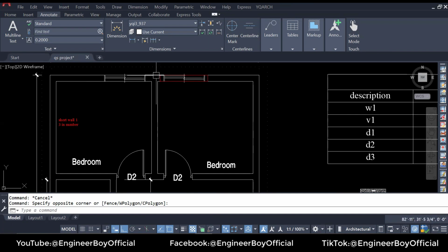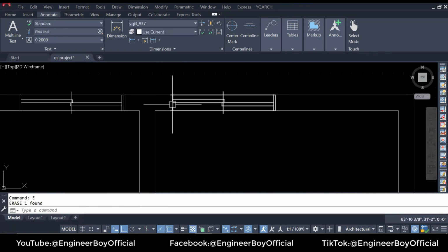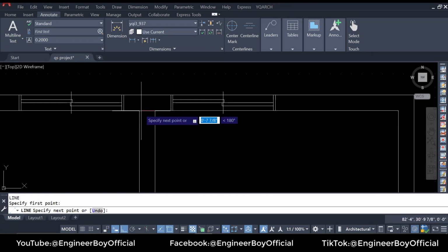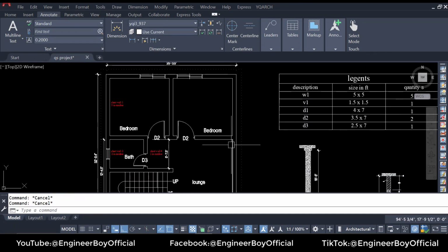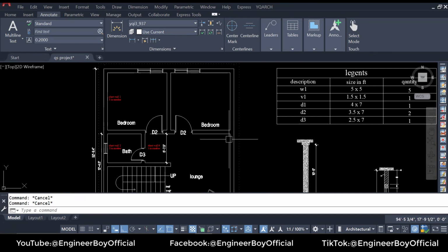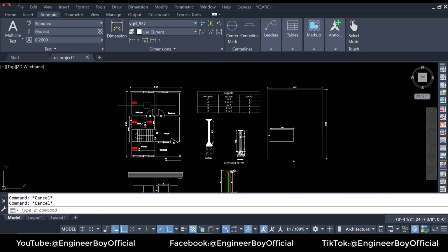But over there, we may have some things. Let's say if we take the long wall, which is just this external one, there can actually be some deductions for this place, because we don't have plaster over here, on both sides of the wall. So it's better to have the parameters and then multiply the parameters with the height. So that can be very easy, okay?